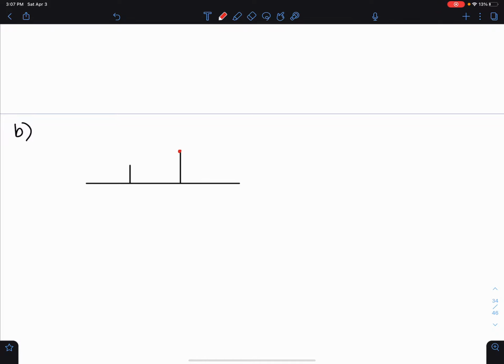I did have a pulley here and here. If I take the pulley out, I have to draw my reaction, whatever's keeping that pulley in place. I have a pin in the middle, so I would have a pin reaction there. I still have the 75 pounds of tension. And then of course I'd have a C_x and a C_y from the pulley at C.